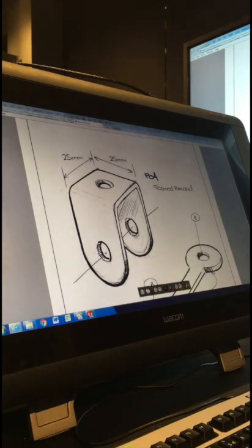So this part, the form bracket, in project 2, we're actually going to convert it to a sheet metal part. A sheet metal part will enable us to flatten it out. So even though it's bent here with the top and 2 sides, we'll be able to flatten it and then laser cut it. In Solidworks, you're able to do that, but one of the keys to flatten it out is consistent wall thickness. You can't have 3 mil thick on the top and 2 mil on the sides. It needs to be 1 thickness. So when we're doing 1 thickness, it makes sense to offset, because offset will keep the same profile, the same shape, and move it all in 2 or 3 millimeters.